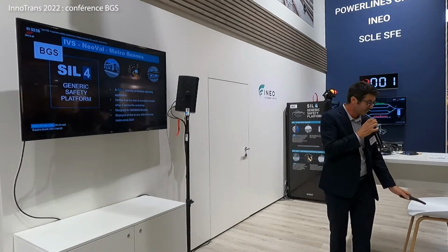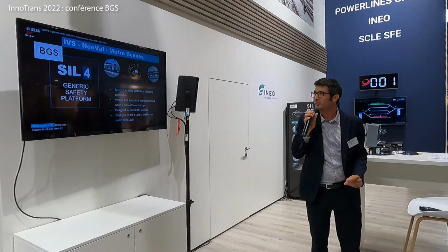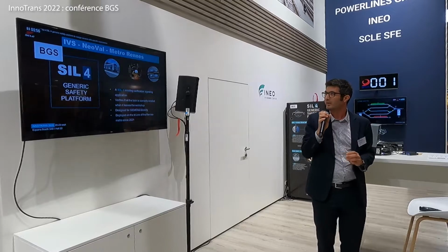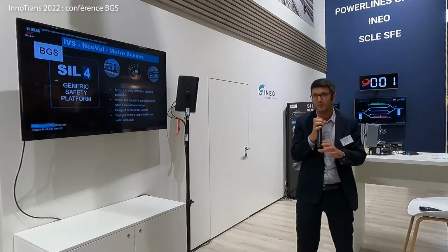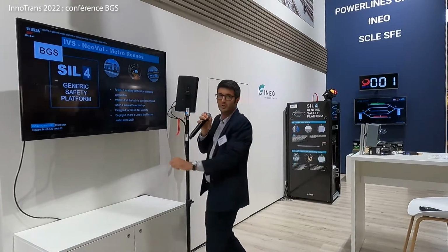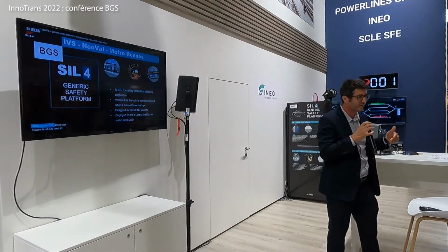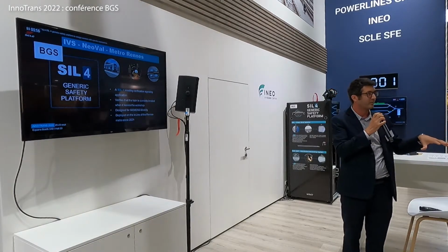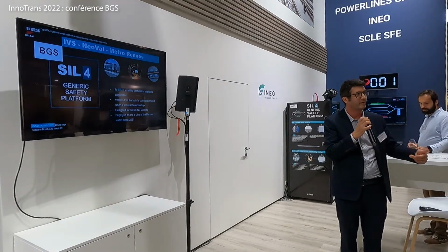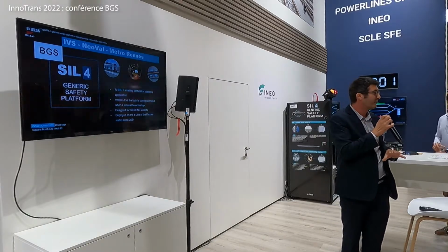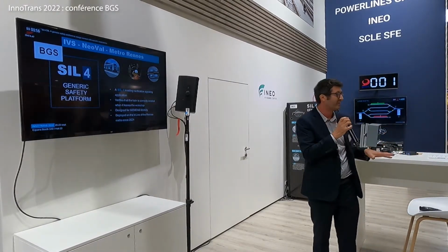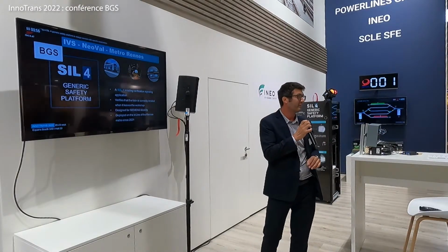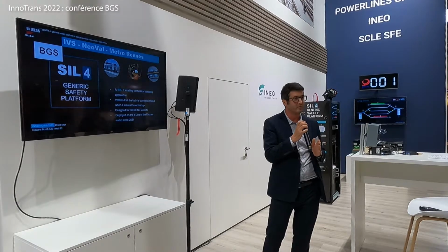Another project is also quite interesting. We did a system for seamless mobility, an in-railing verification system. For the Neoval, they have a central rail which guides the train. In the workshop, this rail is not present, so when the train is going out from the workshop, they need to check that the train is well in-railed. On this project, we did everything ourselves, from the specification to the certification. And we did it in 1 year, from the start of the project to the SIL4 certificate.